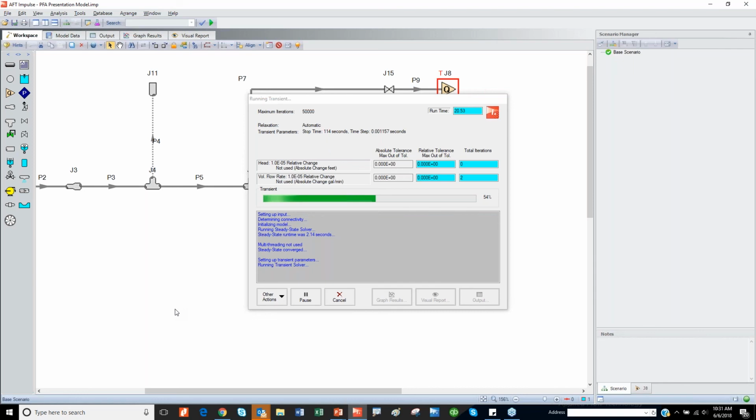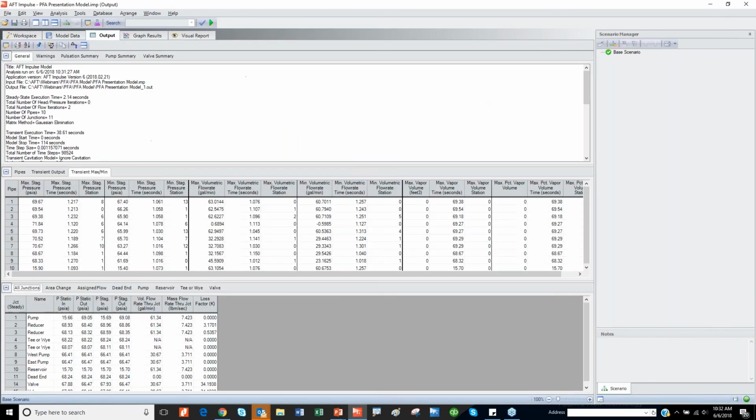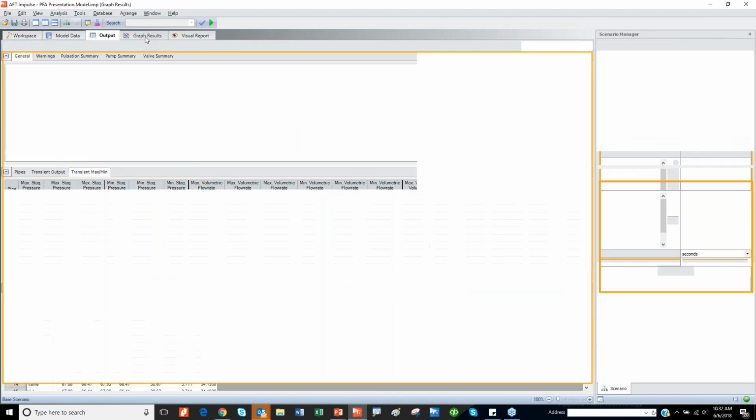So the table shows which pump RPMs will be used to create a scenario. Click the RPM values to select or deselect. The italicized values are deselected. Creating a scenario based on pump speeds: check yes on the confirmation dialog. This will automatically create the PFA scenarios. So once here, it will create the scenarios.